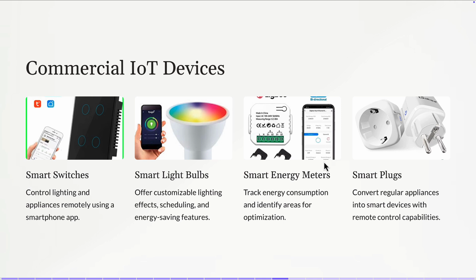So this is smart energy meters. This type of device has sensors here that you can plug into the two wires that go to the meter. The meter always has two wires coming from the electricity. If you put this sensor device in them, it will measure the energy, and also the voltage and the current. And from this you can estimate the energy produced and consumed in your home system. And you can have your energy consumption with all statistics through your mobile phone.